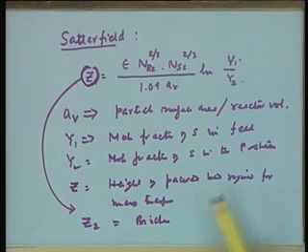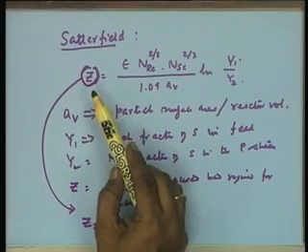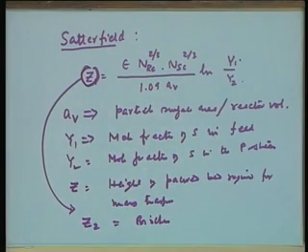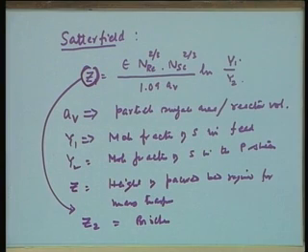You see, normally the substrate is getting transported from the bulk to the surface, and at the surface the reaction is taking place. If there is no reaction taking place, then along the length of the reactor at Z, the substrate concentration will reach Sb, same as in the bulk. It will take some time. Whereas if the biochemical reaction is also taking place at the surface, then the length required will be given by Z2 at substrate concentration Ss. Now, whichever of the two is larger is required to be considered.